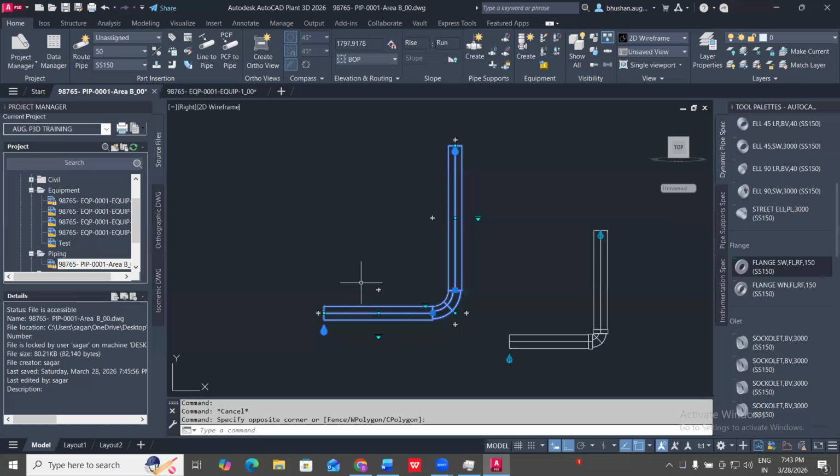It is a single line. You can use bends when you don't want to add welding to your piping, right? You want to bend the pipe, and you can bend the pipe and add your piping to that, like I'm bending my pipe to 90-degree here without adding the welding. So this is the option which will minimize your welding.